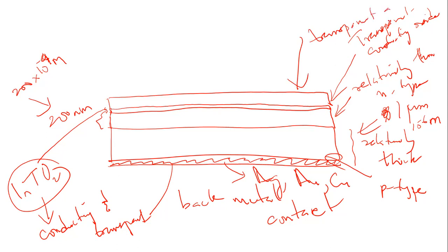Transparent glass. So transparent, it is covered again with transparent glass to prevent the solar cell from moisture exposure and also damage. Like if you put your solar cell on top of your roof, and a certain bird flies by and perches on the solar panel, it can easily scratch this very thin 200 nanometer N-type semiconductor or 1 micron P-type semiconductor.